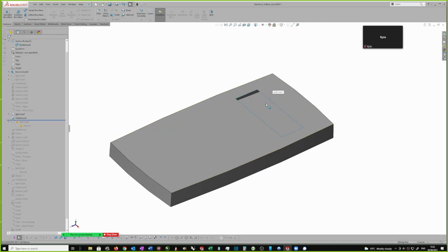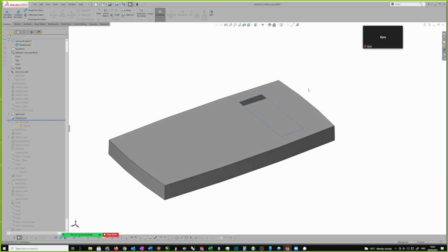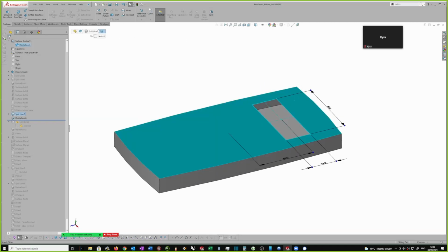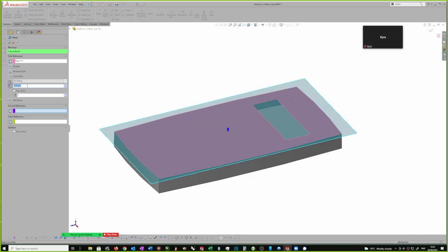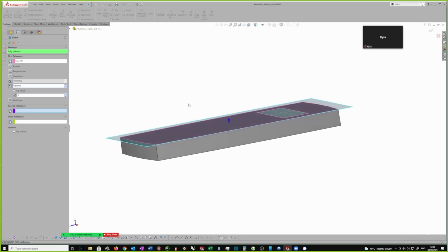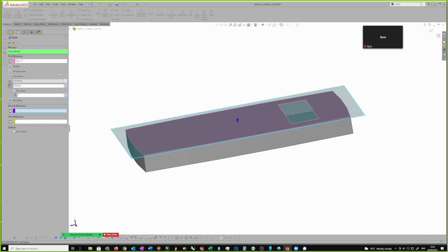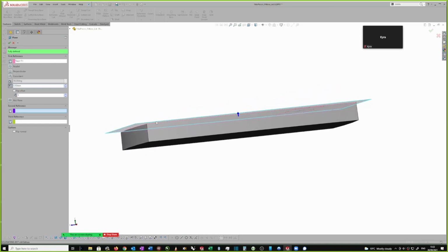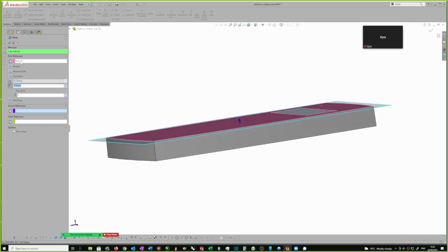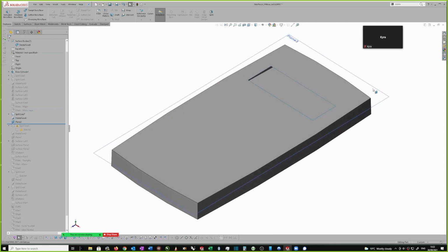So from here, if I want to do some shallow modeling, it might be easier to do it using a plane, which I'm going to offset by, say, 0.5, because we don't have a lot of space. You don't have a lot of space in this box to play with surface modeling. So you want everything to be quite subtle. You can see my surface is sitting above that surface. I just want to flip that offset so that the surface is slightly below. Let's make this 0.6.